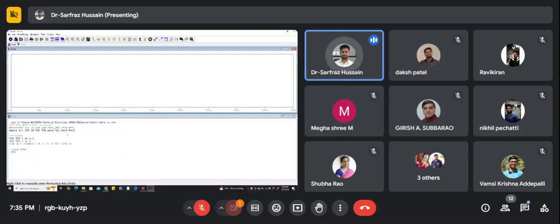Now when you run the simulation, you can see these inputs and outputs. So basically what we did is we created the schematic in the Electric software. We generated a .spi file. We called this SPI file in the LTspice tool, and after calling it, we gave the inputs in this particular format: what is the VDD, what is the VSS, then what is the V input. So we are giving a pulse input to V in. Then we are doing a transient analysis for 500 nanoseconds.